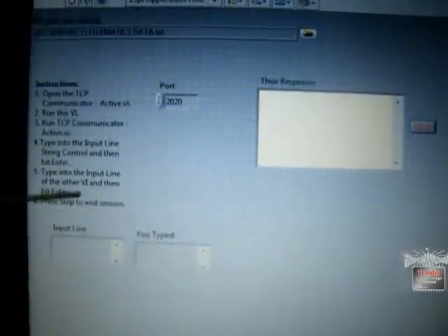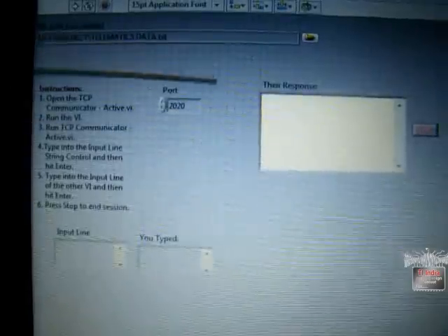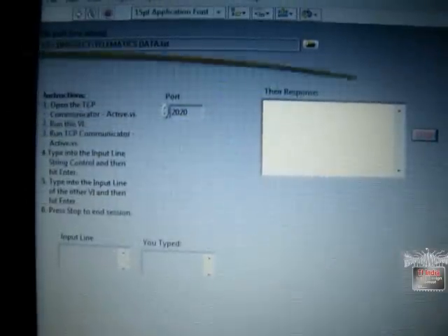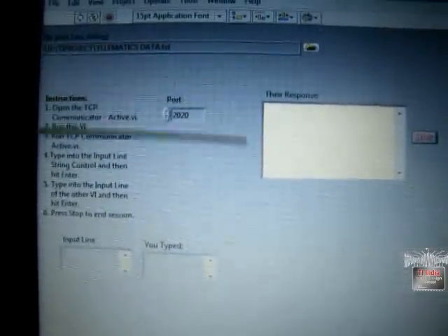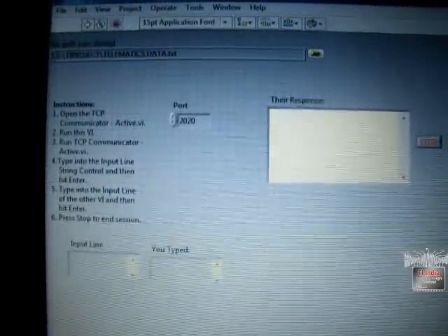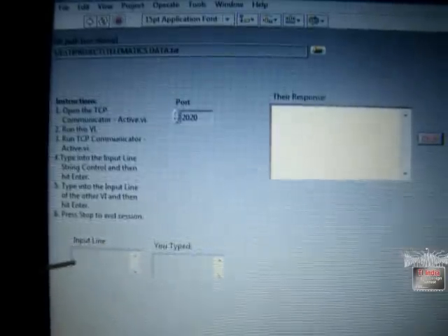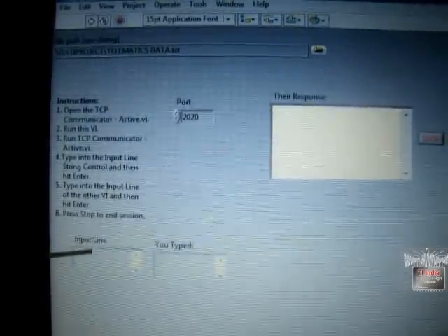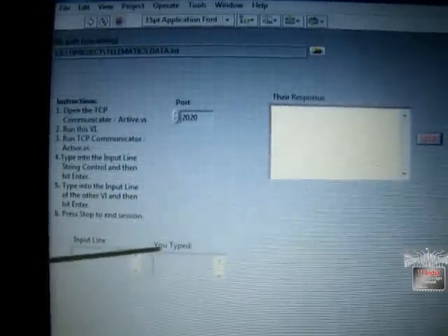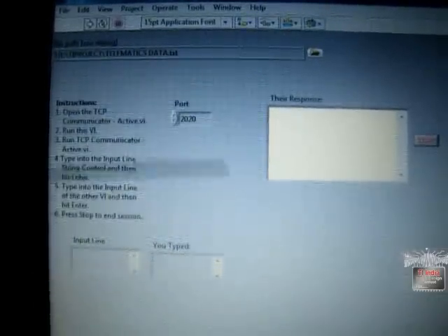This is the LabVIEW server. We have to specify the port for communication, and as soon as the GSM module connects, the response is shown here. All the values sent by the GSM module are received here and logged to this file with the timestamp. Whatever we want to input for future purposes, we have done this. For example, if the vehicle is due for service, as soon as we enter a service alert here, we will get a response that it has reached the destination.